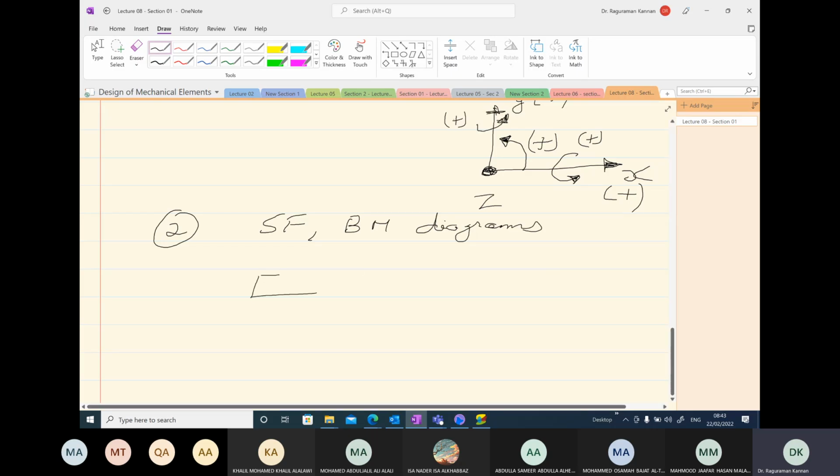Suppose you make a cut on the right hand side of the beam. The internal shear force will always be represented in the clockwise direction; it should lead to clockwise rotation of your beam, which means the shear force is going down. The bending moment should be such that it turns your beam into a vessel holding water from the top, so concave on the top.